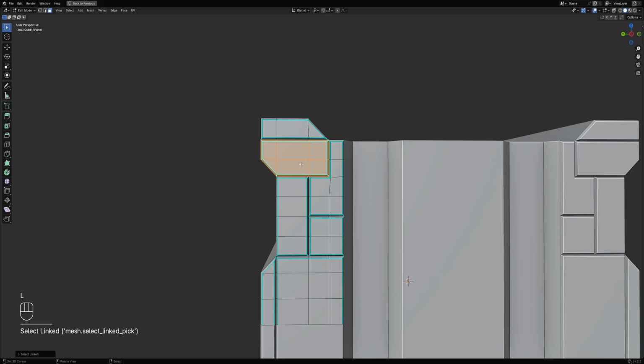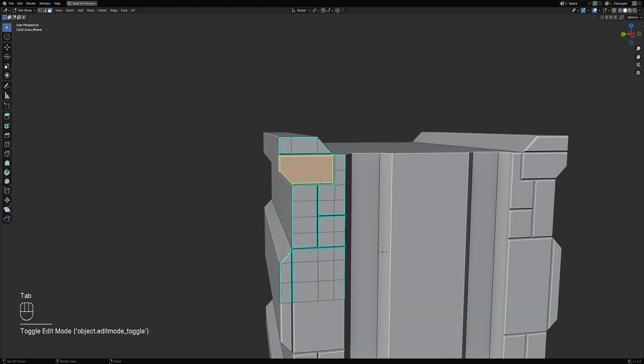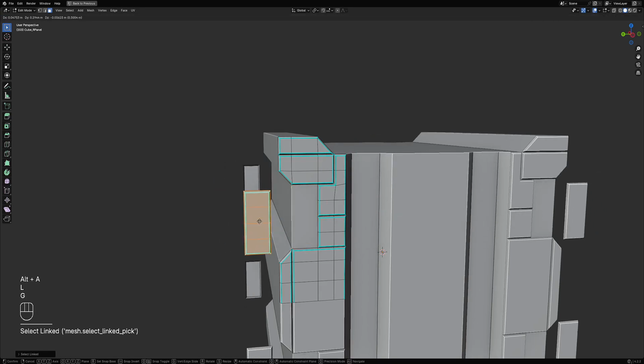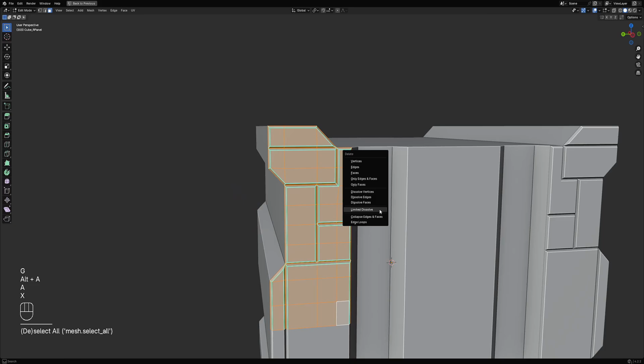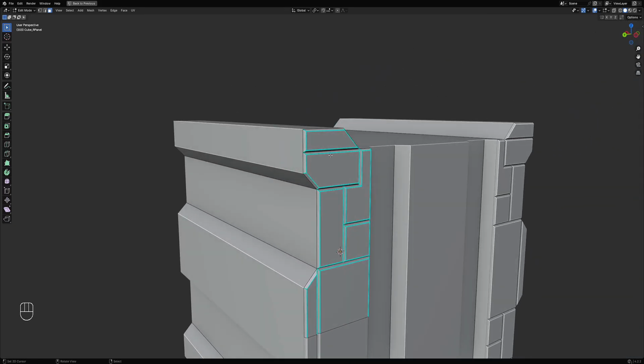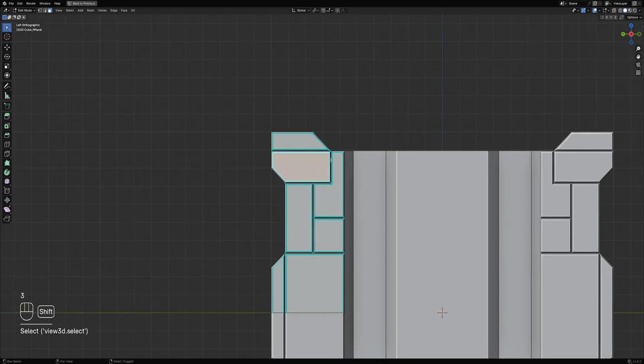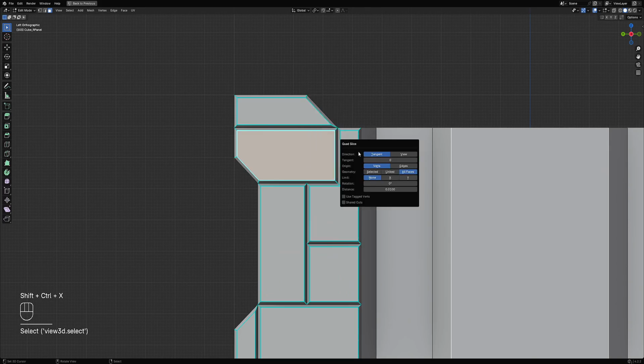By default, this is another object, a non-destructive operation, and each of these panel islands are separate sets of faces that are disconnected from the other islands. If we limit this, we have these faces, but the shapes remain intact. If we want to quad slice this, you can see that with selected, only the selected face becomes quadrangulated.